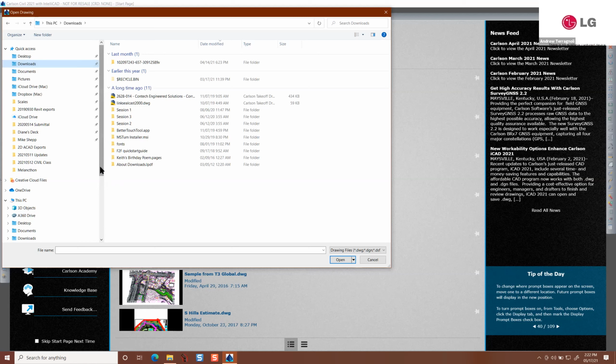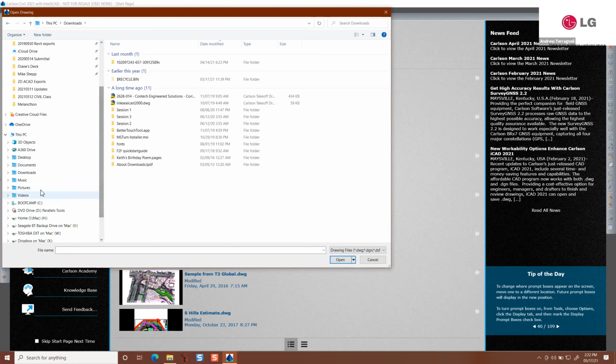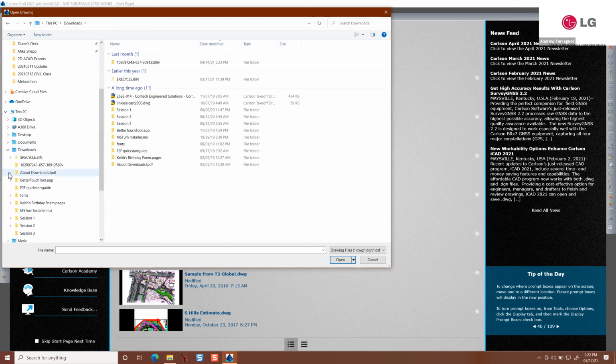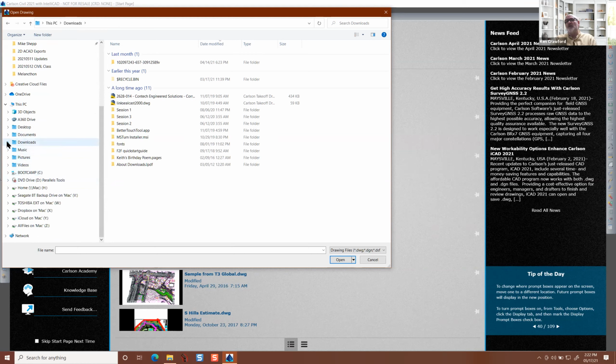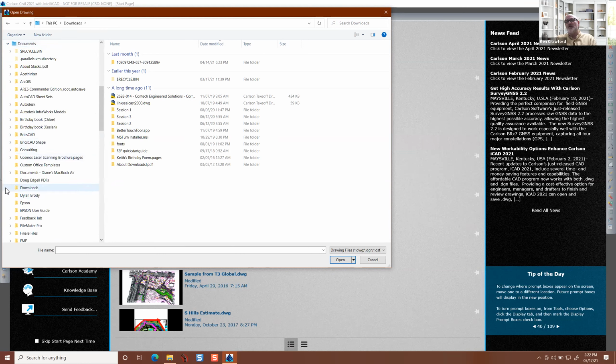Interesting. Okay, yeah. So we just change the stationing when you snap them together to make it look like one. Yeah, because I ended the first alignment at, I don't know, station 2+00, some even nominal station, and then picked up the second one right at that same spot. So what we had to wind up doing was run the first one and then find the elevation for that ending station, to make sure that was the starting elevation for the second one.